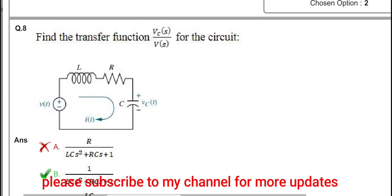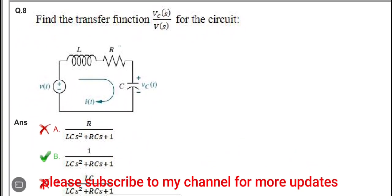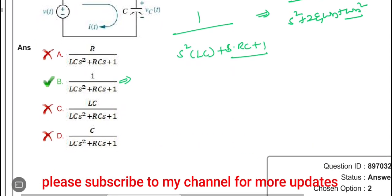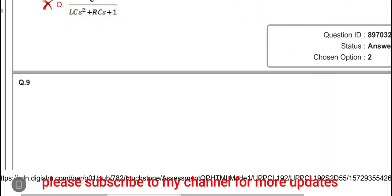This question is from control systems. The transfer function Vc of S by V of S for the circuit is shown in the figure. You can directly substitute and get the answer. It is 1 divided by S square LC plus S RC plus 1. We can compare this equation with the standard equation in control systems, omega n square divided by S square plus 2 zeta omega n S plus omega n square. So you can substitute and you will get the same answer here. If you have any doubt, you can comment, and I'll explain it in the coming sessions.